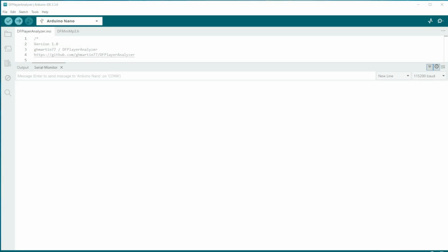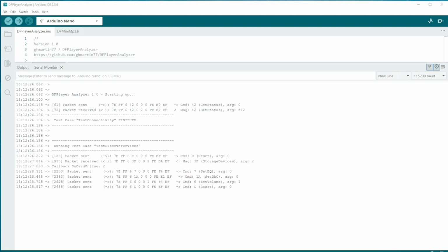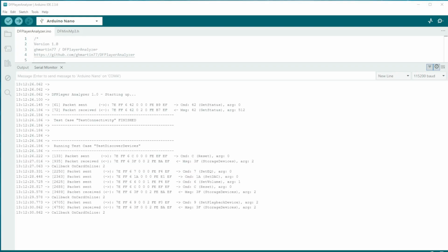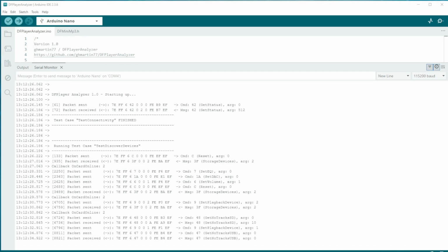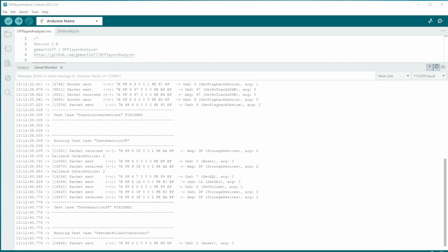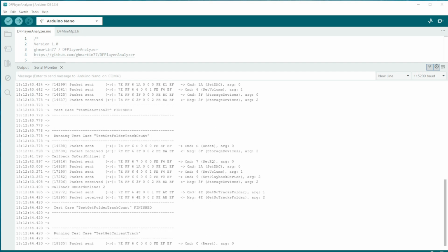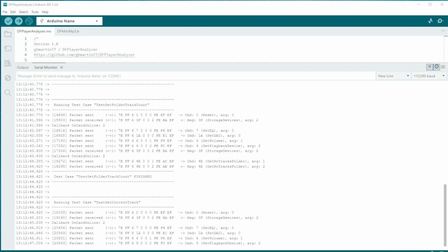As I was doing some searches on DFPlayers, I found this analyzer test, so I ran it on the devices. I had issues running with sleep and adverts, so I disabled those tests as they were not of interest to me. Most devices responded well. One surprising issue was with the two JL chips. The older AB version did fine, but the AF that I recently received had a failure in the test track finished callback.